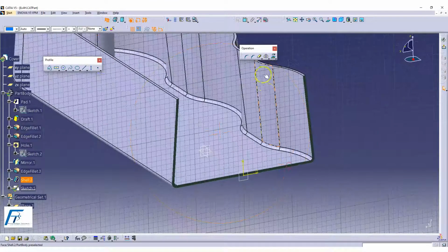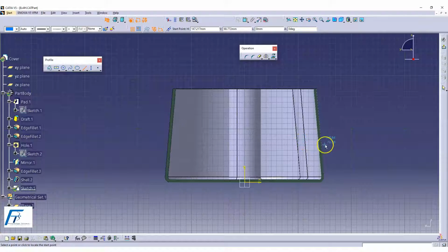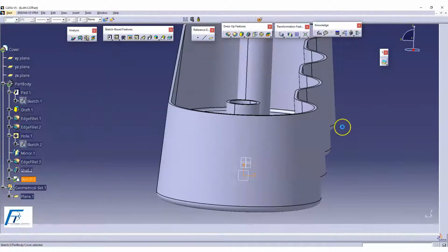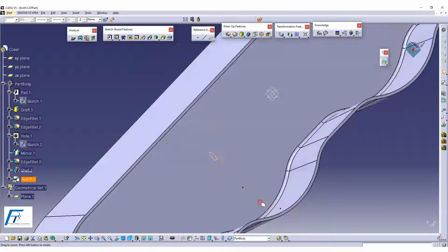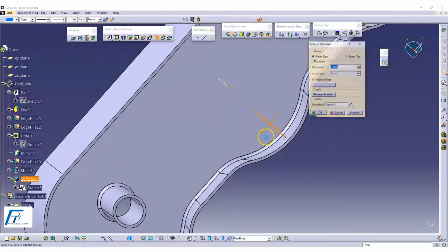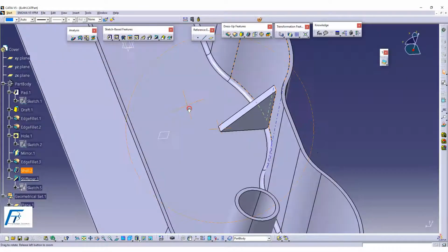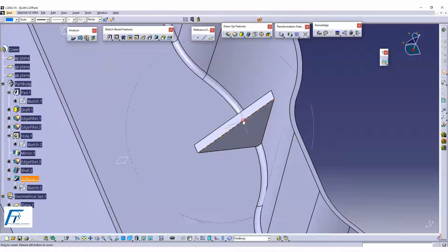You can see this. And it's not mandatory that always your sketch has to be normal to you. You can just draw a line and constrain it. See, I'm just going to draw a line and constrain it. It's not mandatory that it should be constrained. But the moment you just draw a line and see that this line is appearing over there, I'm going to create a stiffener at that particular point. And it's going to increase by 10 mm. So your stiffener is created at this location. See this.